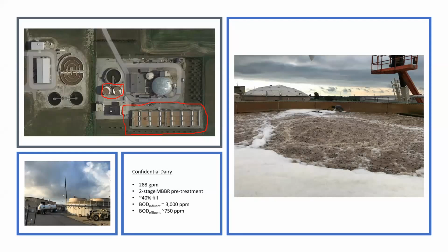We see this a lot in industry, where clients can't afford to stop the wastewater treatment plant because they can't afford to stop their production process. I should note that in these cases, we either look at a retrievable aeration system or we look at coarse bubble. While our preference is fine bubble, we do recognize that there are many cases where coarse bubble makes more sense for the client.